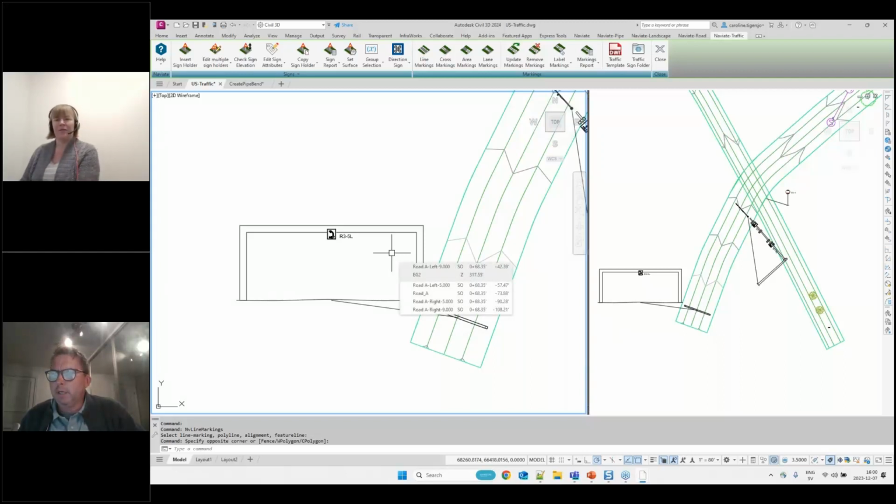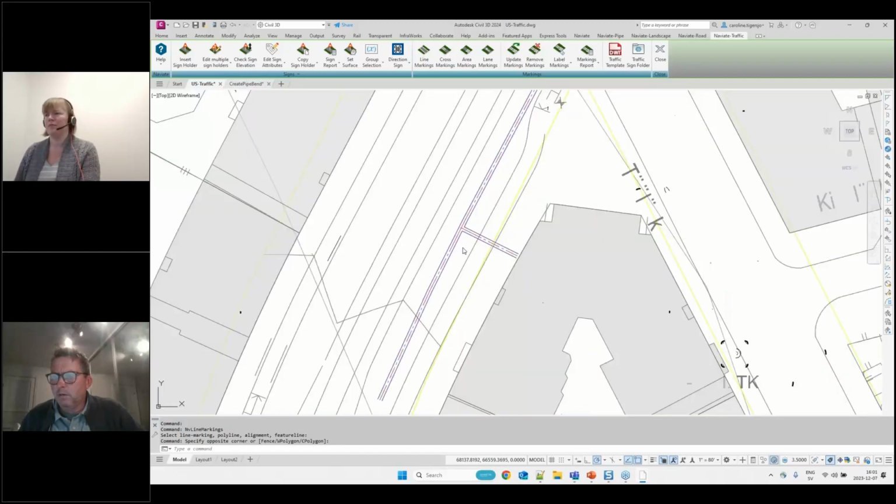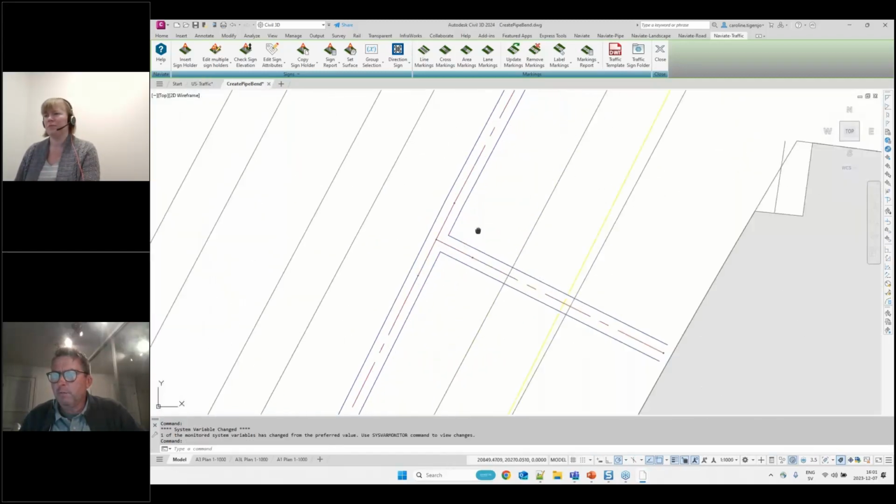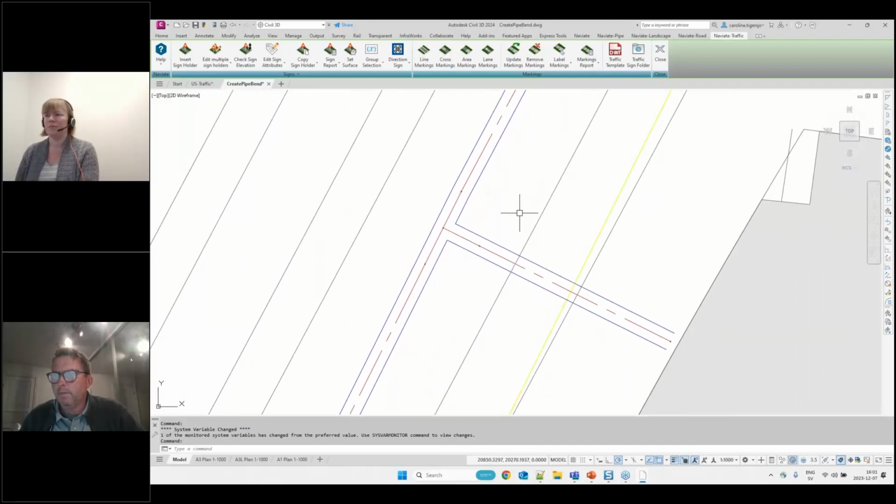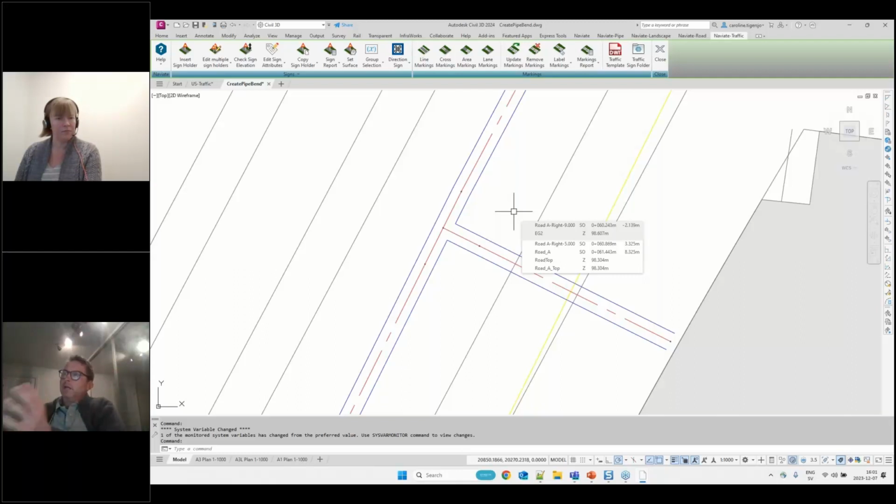And otherwise, let's see, I have one more question I didn't answer. The alignments still are one during the whole process of copy and merge corridor. Corridors only with the same alignment can be copied or merged. Now you can add a baseline. So, if you have two corridors that run either after each other or beside each other, you can add them to get multiple baselines in the same corridor.